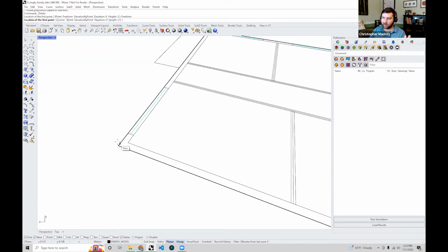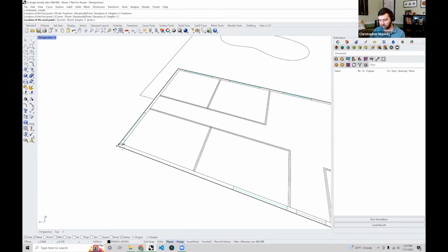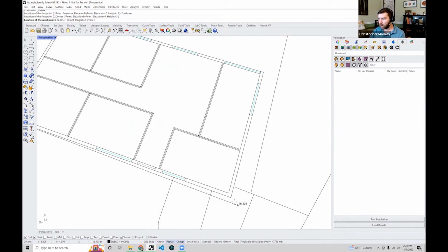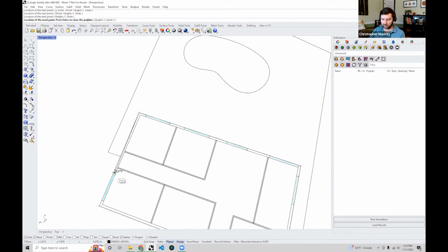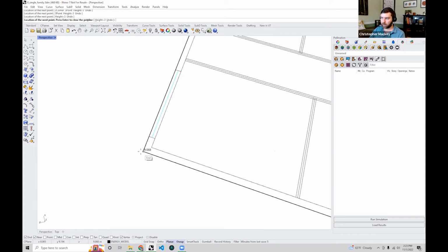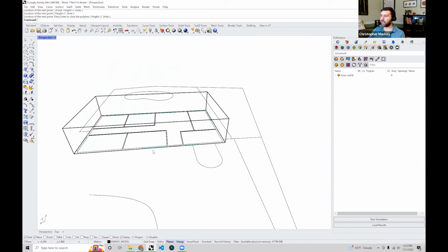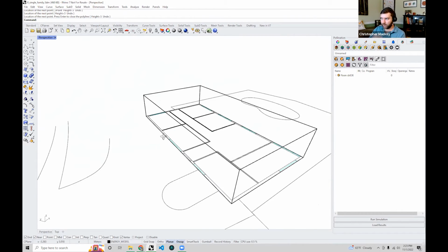The important thing to have for now for the workshop is to make sure you have end selected so that you can easily snap to these different corners of the actual plan that we have here, instead of just trying to blindly trace it. That'll at least make sure that the model you're making is a good representation of the actual real building, instead of just trying to eyeball it and potentially getting a little bit off from the plan.